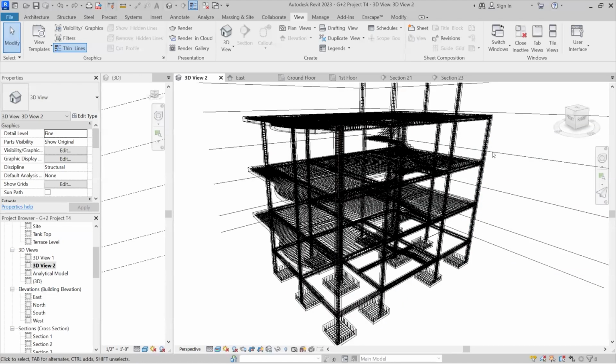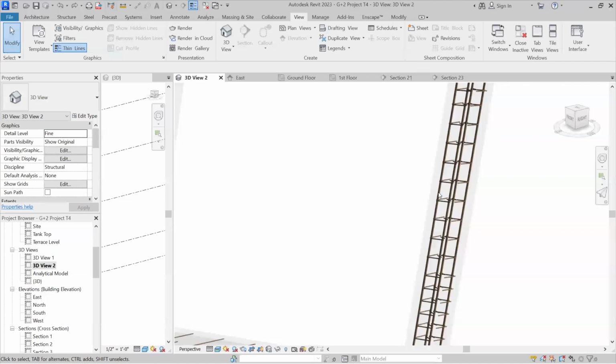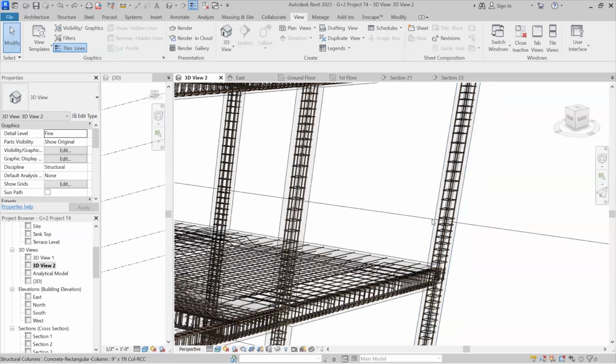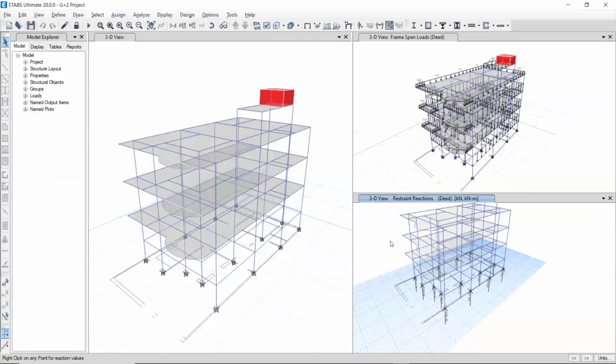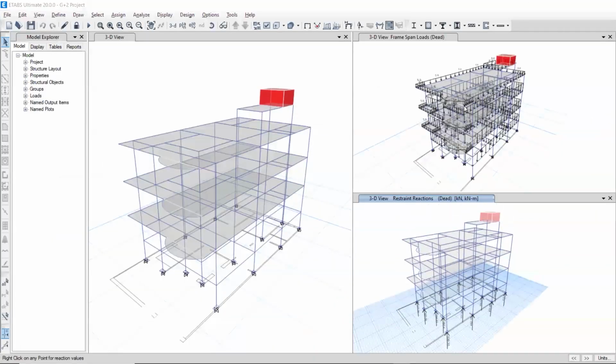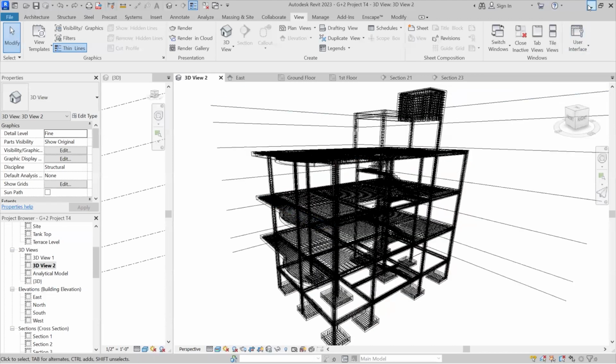By one click, you will be able to place rebars in this entire column, and later on you can change the dias, the spacing of these rebars, the amount of reinforcement it is going to receive. So you're going to take the final results from the ETABS software, and then you're going to put these into this Revit software. So for learning purpose, place it by hand, and after that use those plugins that I have taught in the course to quickly place reinforcement in this structural part.